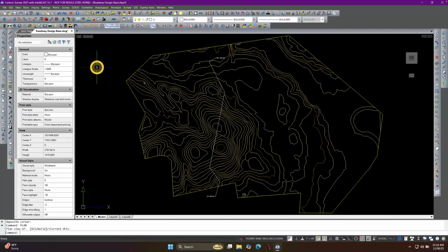If I explode it once, this thing called an AECCDB surface 10 would explode into a block, because when that surface was created, AutoCAD or Civil 3D created the block of all of these, in this case, drawn contour lines. It also created another block of all of those rotated triangles. It just stores those block definitions and brings them forward depending on which view perspective you're using.